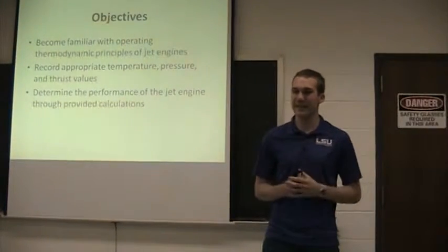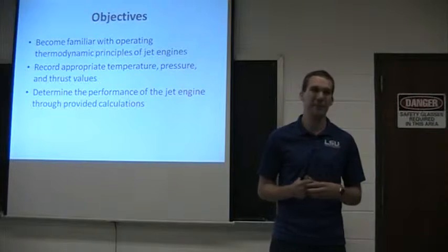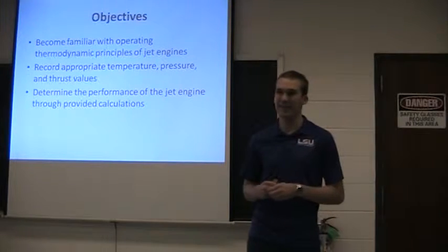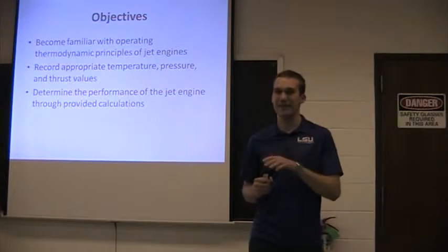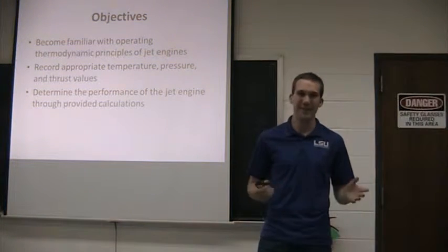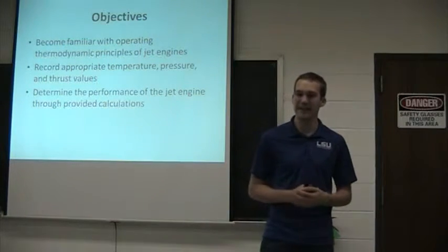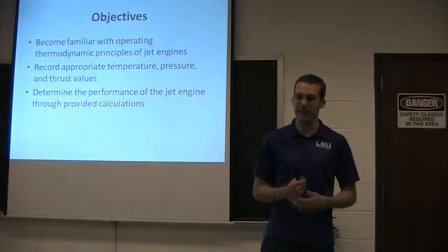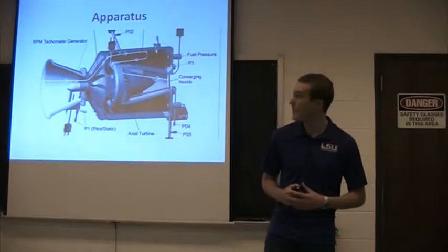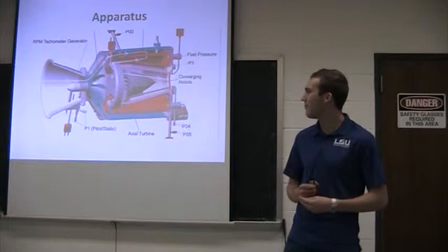So some of our objectives. The purpose of this experiment is to become familiar with operating thermodynamic principles of jet engines. Basically, we want to dissect the cycle and see different pressures and temperatures at the operating points. We want to do good housekeeping work in a sense. We want to record appropriate temperature and pressures, as well as thrust values, and ultimately determine the performance of the jet engine.